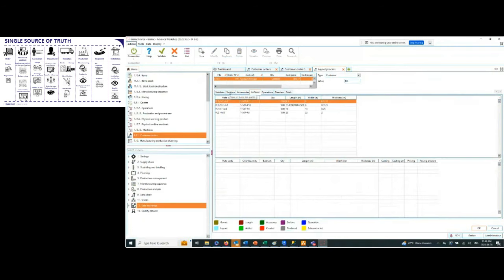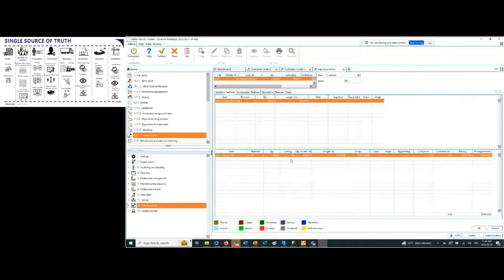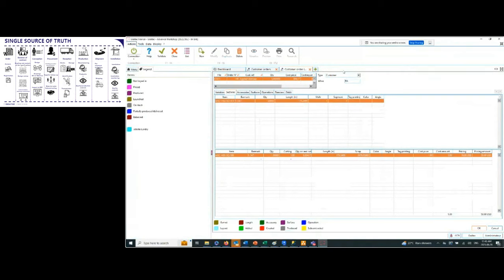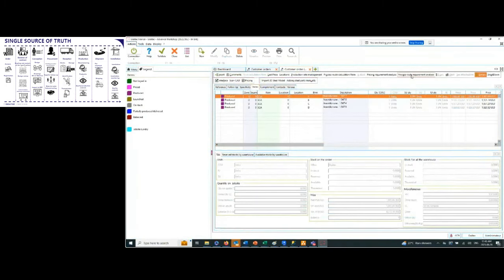Here you can see surface area consumption for the plate, and here length consumption for the profile as well. Now here when you see scrap of X amount in length, of course this is something that can be managed. So you could write rules in the system for certain types of elements that if it could exceed 2 feet in length on the drop off, you would want to keep that in stock as opposed to chucking it to the bin. Okay, so this is how you get a high-level overview of how it's broken down, the cost per operation, theoretical time per operation, and which items would need to be utilized to execute the assembly itself.